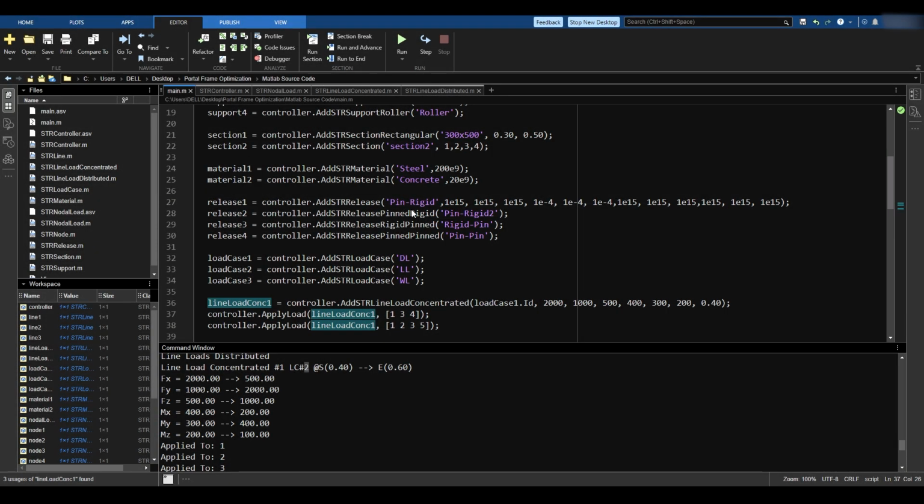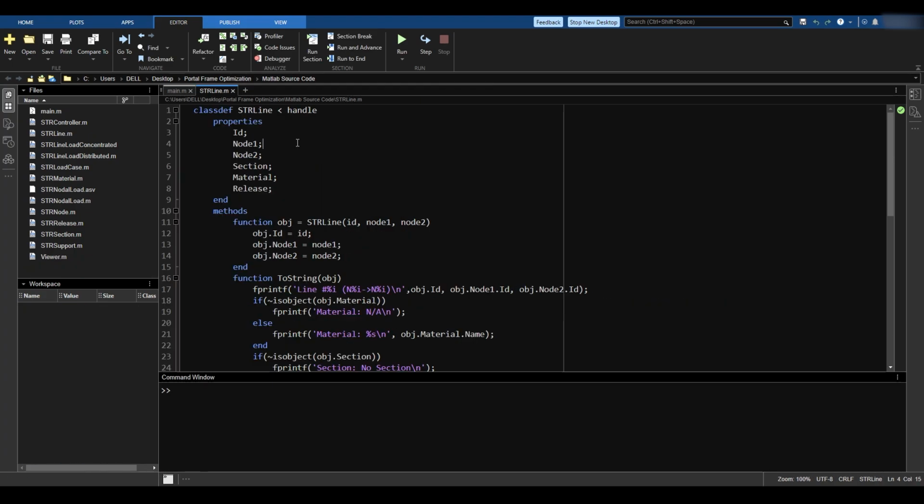So now let's be technical a little bit. To be able to perform anything with the finite element method, like calculating the global axis, calculating the global stiffness, and transforming from the global to the local, we need something called the transformation matrix. And to be able to calculate the transformation matrix, I need to know the local coordinate system of an element. The local coordinate system of an element is the local x-axis direction, the local y-axis direction, and the local z-axis direction, because using those I can construct the transformation matrix.